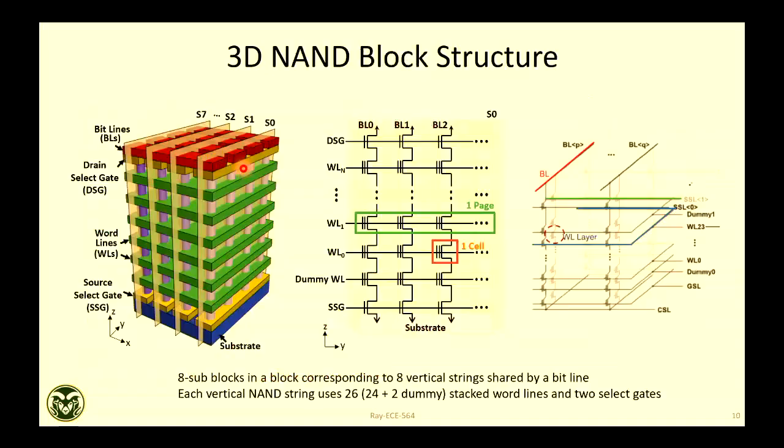Okay. So this is what your block structure will look like, and if you take a slice, like cutting a cake, for example, this will be one block. This will be another block, because one block shares the same bit lines. The bit lines are common. Bit lines are global lines, and across the block they will be the same. That's why they are big, gigantic lines. Capacitance is huge. When we talked about DRAM, we saw DRAM bit lines are huge. So bit lines are thick copper lines. They will be global for a given plane of the memory.